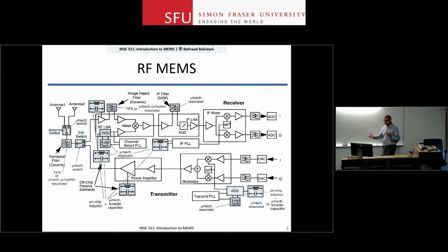And because of the standards and requirements, legal requirements, each system can only operate in a certain portion of that spectrum. So you need to go and, let's say at 2 gigahertz, have a filter that cuts out, let's say, a 10 megahertz portion of that frequency band, and all of the information that you're sending and transmitting can be in that band. However, if you switch transmitter, if you switch to a different station, or you need to use a different band, it's a different frequency, different spectrum.